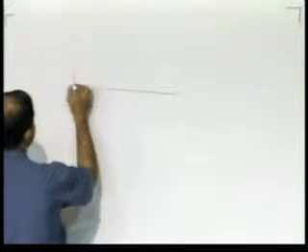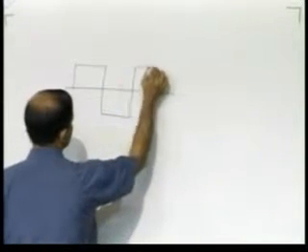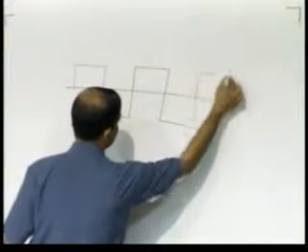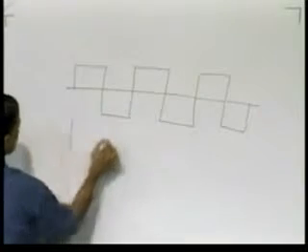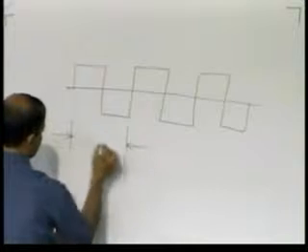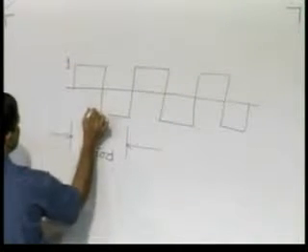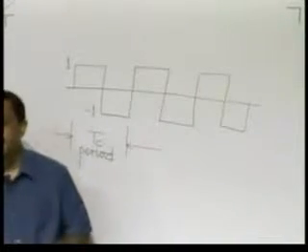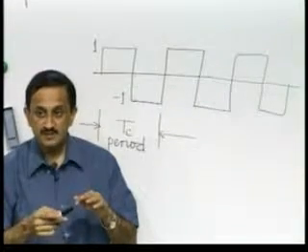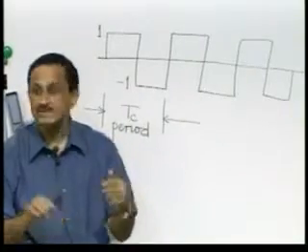Now, at that time we made use of a sine wave carrier. But suppose we do not have a sine wave carrier, right. So, suppose we have a square wave carrier, which might be easier to generate at times. Actually, what I mean by a square wave carrier is a gating pattern. This is what I mean by a square wave carrier or a gating pattern. What is a gating pattern? A gating pattern is a waveform that either passes the incoming waveform as it is, or passes it inverted, or does not pass it at all.